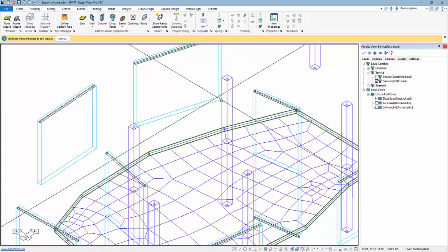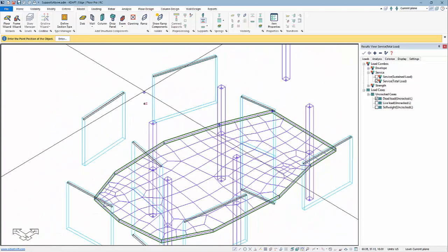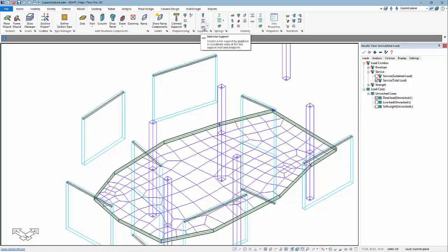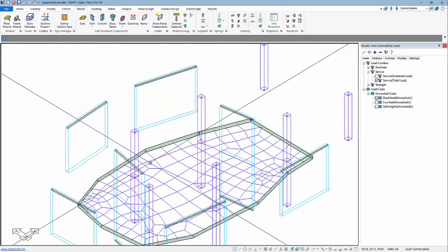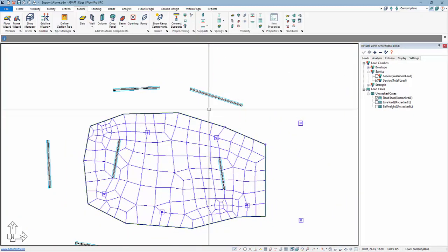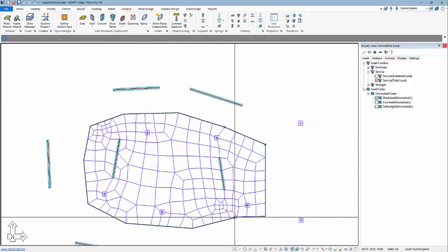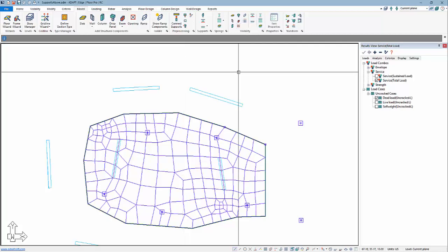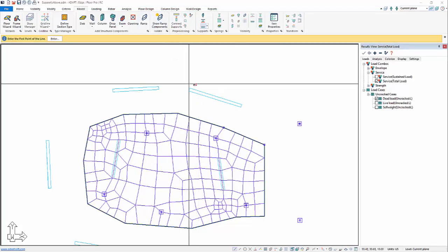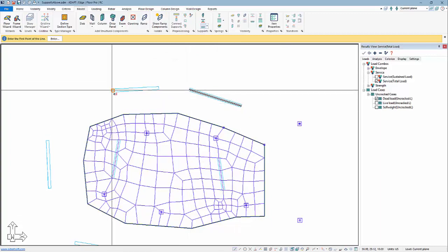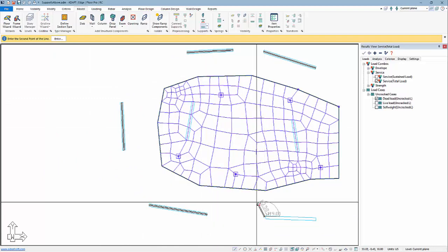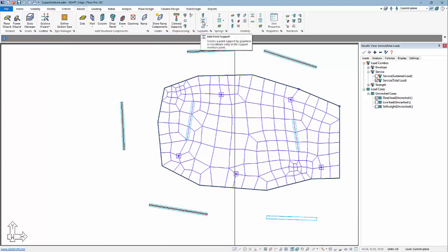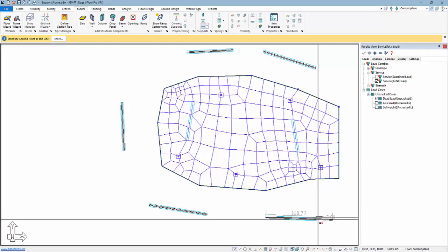See if we can grab that location. Still have a point support there. Let me make sure I have the line. There's a line support. We'll go from point 1 over to point 2. So go to this view here, and I'm going to turn off the view of the supports. We can do that from visibility. Okay, we'll go to this option for line support. This is not to be confused with the automatic supports created at the top of the walls automatically.